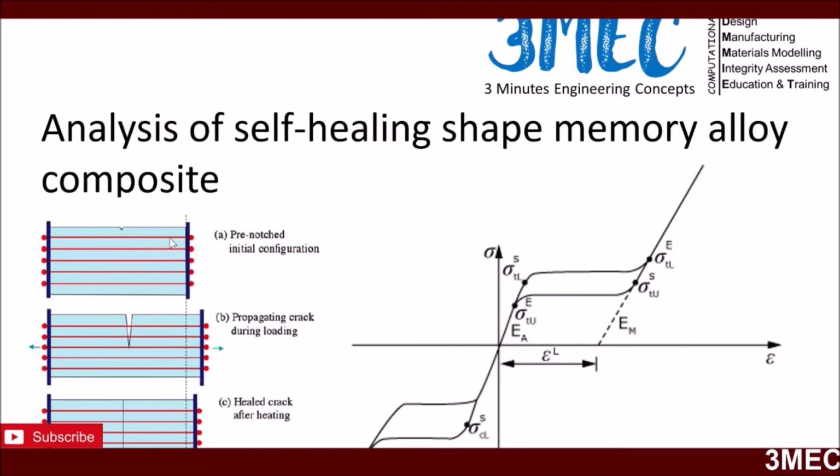First, I will show you how to model this fiber using this pseudoelastic response in ABAQUS in today's video. In the next video I will show you how to model the fracture if you have only the matrix, and in the third we will integrate these two components together and do the actual simulation, but again using a fictitious set of parameters, and I don't want to really give you the whole solution. So let's move to ABAQUS and see how we can do the pseudoelastic response simulation for a shape memory alloy only.